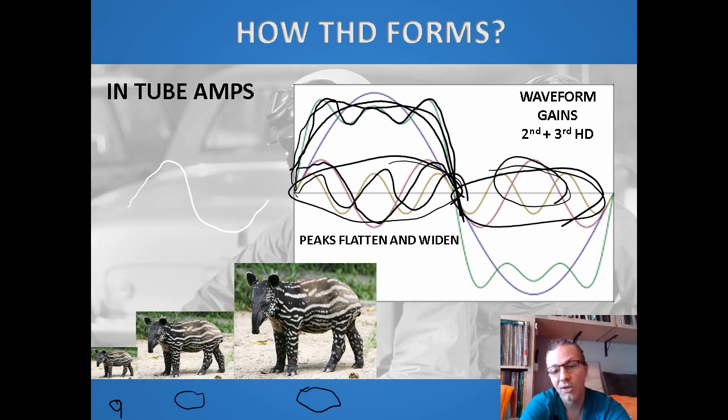It's because there you need to get the biggest cone movements, and there the cone is not coupling to the air of the room perfectly, so you have tremendous issues there. And also for tube amplifiers in the bass, that's where your output transformer's inductance starts to become limiting.